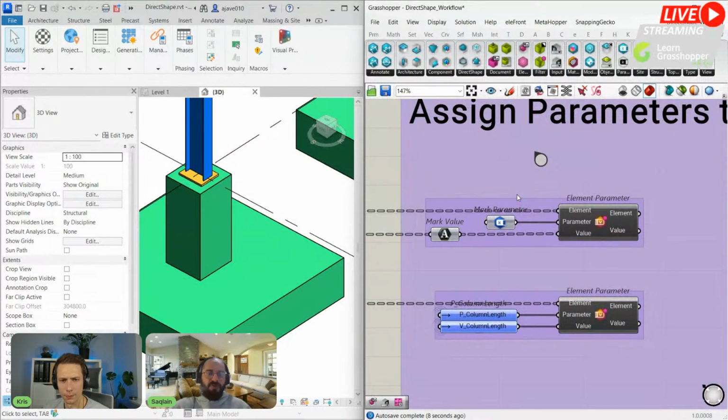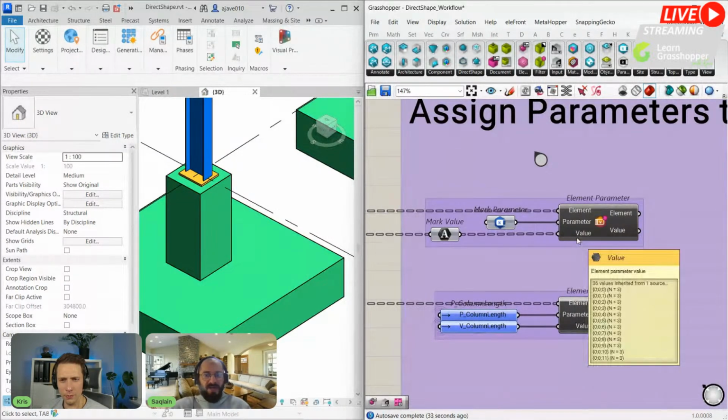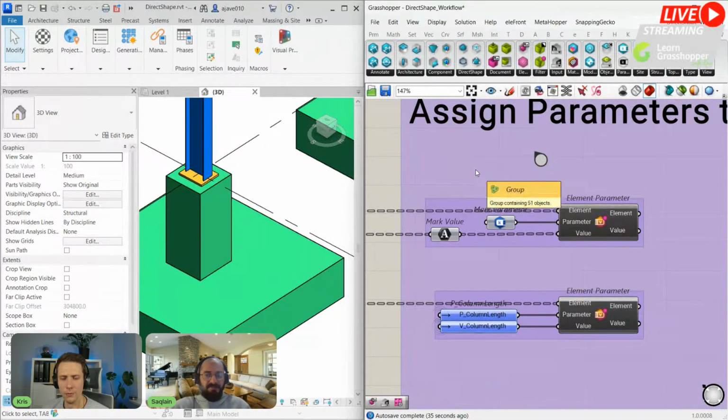You change from instance to type. So most often we have these problems. We have created the shared parameters, but we cannot assign these parameters to our family. So that would be the case. You have defined your parameters as type, not as instance. So whenever you see read only here, just try to check if it's an instance or type parameter. This workflow works for instance parameters, but if you want to change into type, then you need to use the element type parameter here.